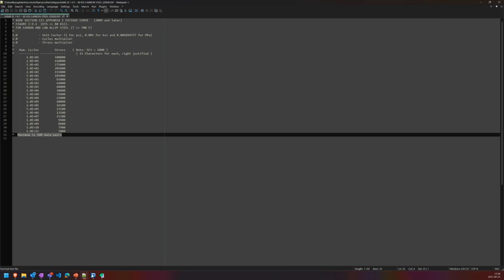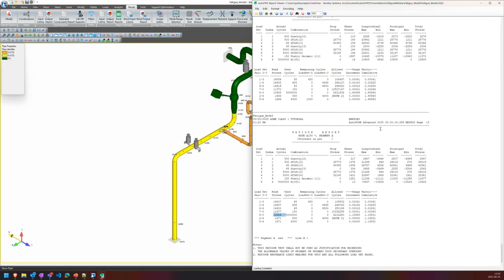Please explain the 2 billion cycles. So 2 billion cycles is just a limit that we have. From what I understand, normally anything above 1 million cycles is considered the endurance limit, which means that it won't cause enough damage to fatigue. It may vary from industry to industry. We have limited it to 2 billion. It's a relatively arbitrary number, but we feel confident that anything experiencing 2 billion cycles, that's a lot of cycles. And so we've used that limit.